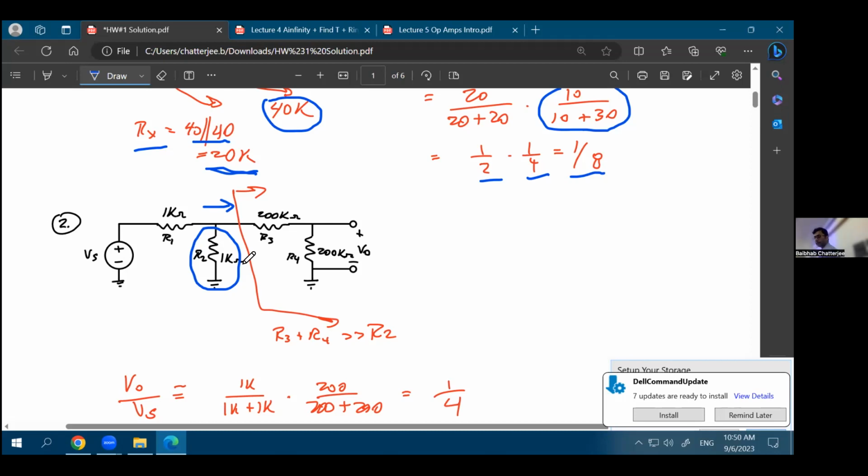And that is something of a valid assumption, because again, as I talked in the class earlier, all electronic components have some kind of tolerance. So if you have a 1K resistance, it can never be exactly 1K. It could be 1.01K, it could be 0.99K, it could even be 0.97K. You do not know the value exactly, and you cannot control that value to that much accuracy. So what's the point of doing that exact calculation?